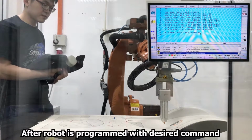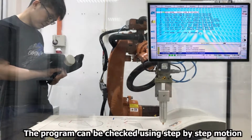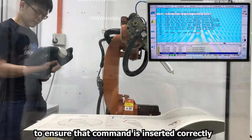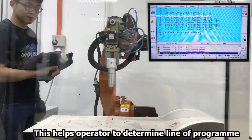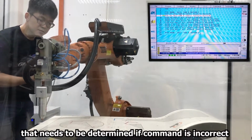After the robot is successfully programmed with the desired commands, the program can be checked by using step-by-step motions to ensure the programs have been inserted correctly. Besides that, this could help the operator to determine a line of programs that need to be corrected if the command is incorrect.